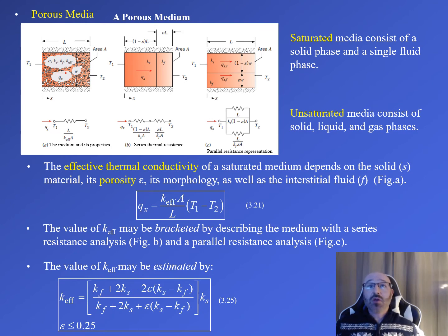One thing that we want to look at is that there are two different types. We either have saturated or unsaturated. In the saturated situation, the media consists of a solid phase and a single fluid phase, whereas an unsaturated media consists of a solid, liquid, and gas phase.